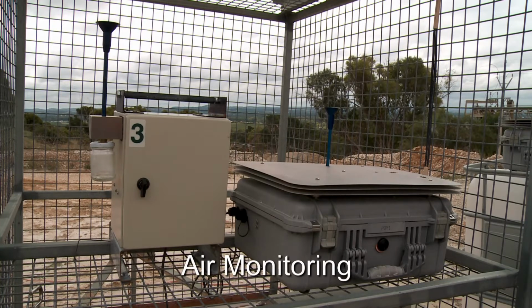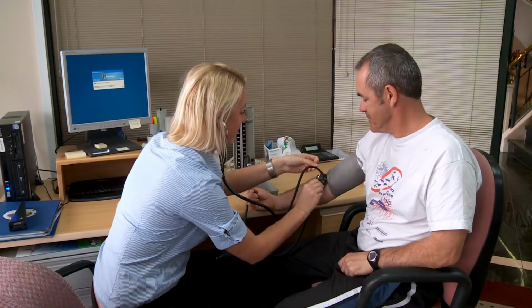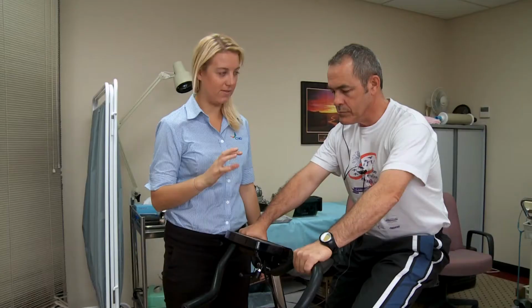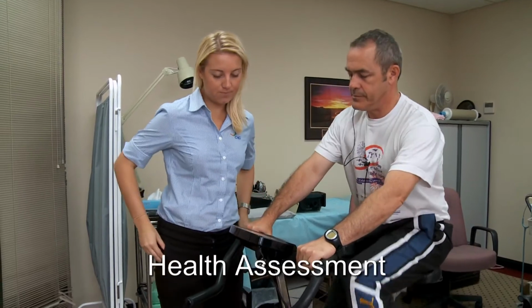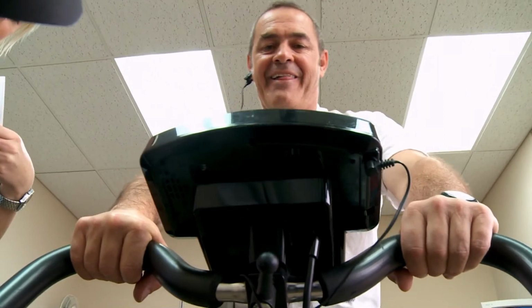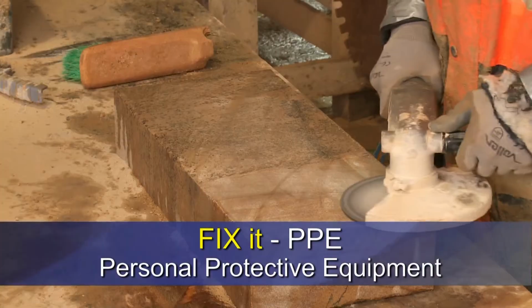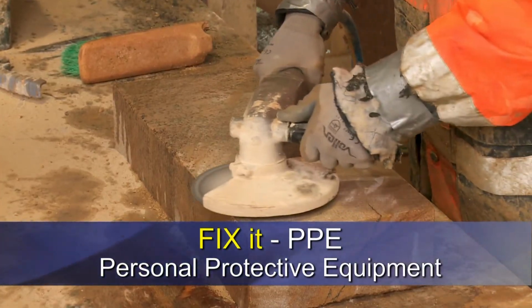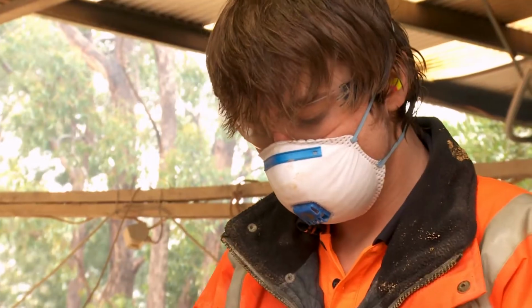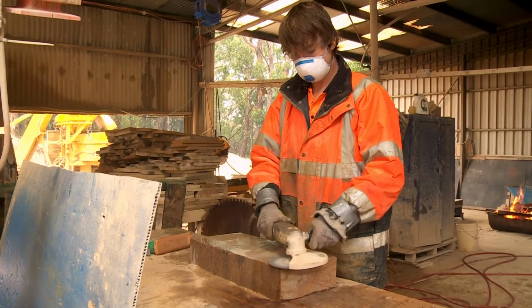Regular air monitoring can detect hazardous materials and measure possible exposure levels. If hazardous materials are detected by air monitoring, then regular health assessments are necessary to compare the results with industry standards and help assess the likelihood and consequences of exposure to dust. Personal protective equipment, PPE controls. Personal protective equipment is the last line of defense. Wear respirators to reduce dust exposure.